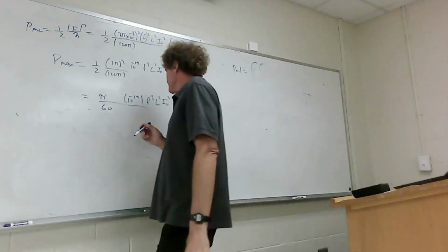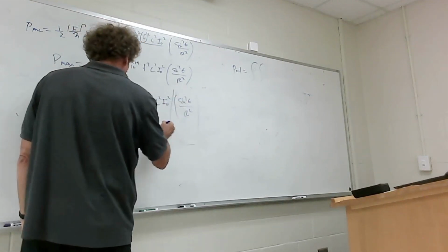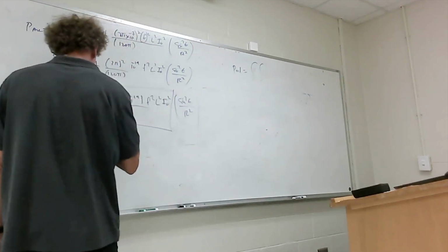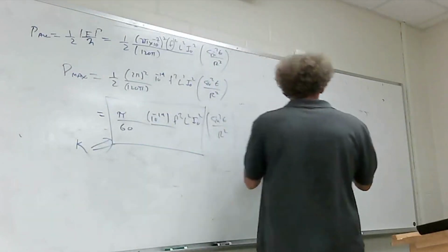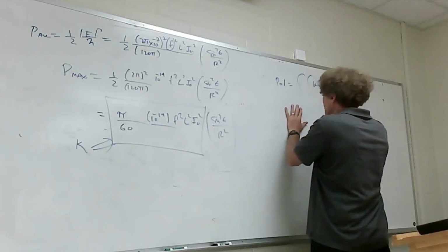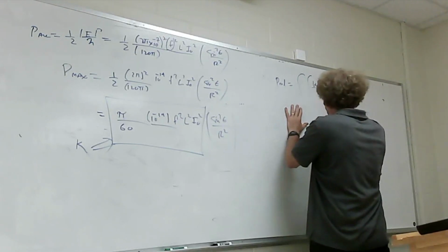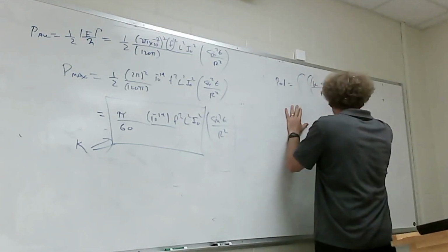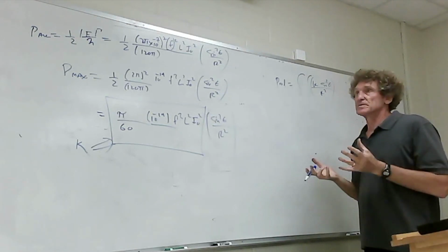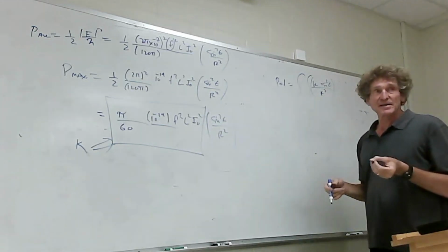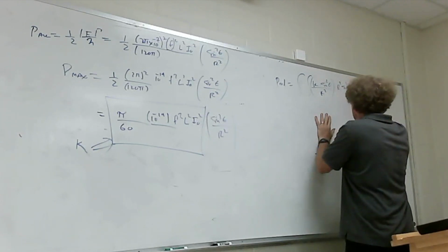So let's try to get some constants down here. What I'm going to do is take this entire mess right here and just call that K. And so I got K. Then I have sine squared of theta over r squared. That's the average power density. Now I have to multiply by the differential spherical surface. Do you remember what that is? r squared sine of theta d phi.